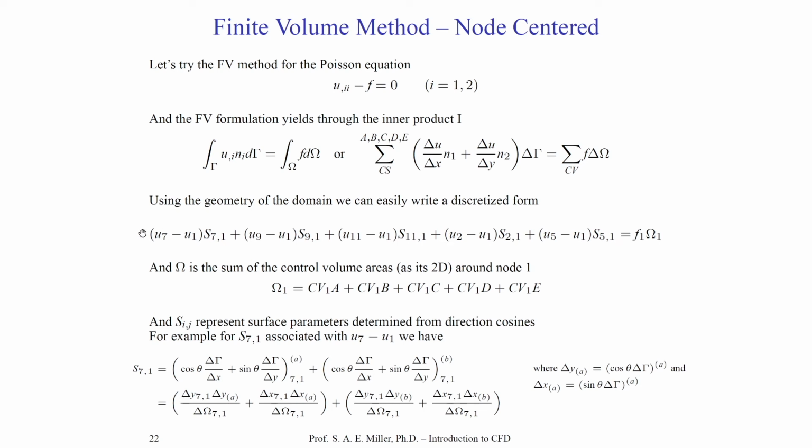And so this would actually be one equation which is conserved at each particular volume. If we have the Navier-Stokes equations, which would be 5 plus a gas law, we would actually have multiple equations and fluxes written. So we might have 5 equations in 3D written across and for each volume. So if you have 10 volumes, you would have 50 equations found from a Navier-Stokes system. If you have 10 volumes for the Poisson equations, you'd of course have 10 of these equations.